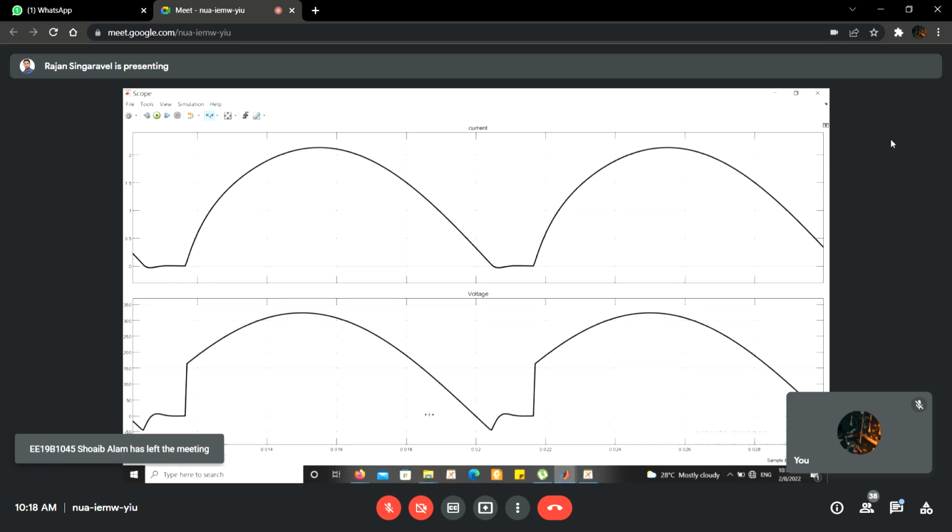So the load angle determines for how much time the current will stay positive, and alpha is the one which decides the firing of the next pair of thyristors. So now we can come to a conclusion from these waveforms. When the load angle is greater than alpha, even after pi degree, at some point of time the current will become zero at omega t equal to pi plus phi.